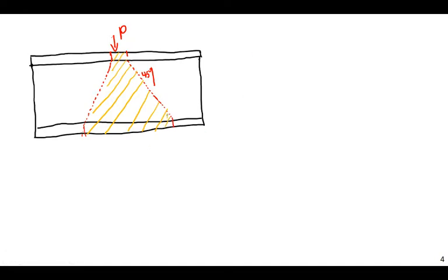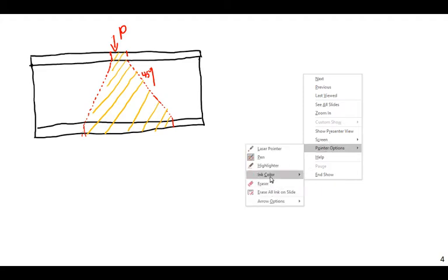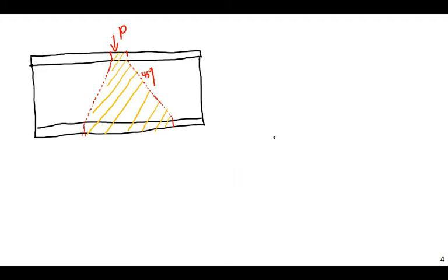So this is sort of a local stress. This point load has to distribute throughout the rest of the member. Because of this, the entire beam is not going to be able to resist the vertical force of this point load. Only this portion of the beam has to do that. So what this comes down to is, inside every beam, whenever you apply a point load, you effectively have a very weirdly shaped column. It's kind of shaped like this.